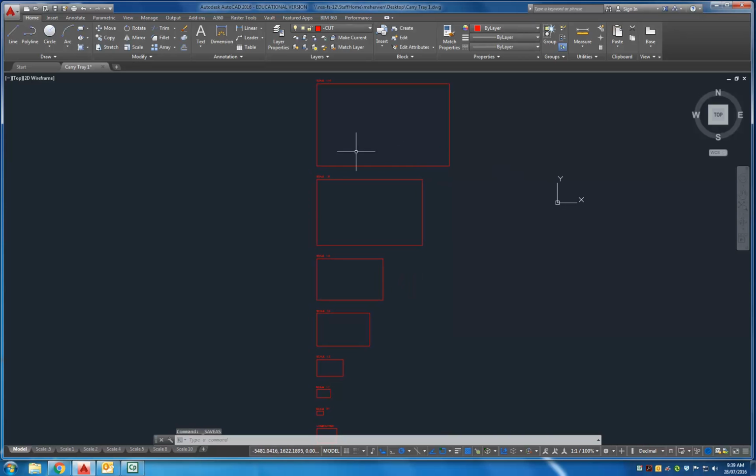From there, I just want to talk quickly, before we start, about what this space is. This is called model space. This is where we do all our drawing. For example, we first find which scale suits our drawing best. If you're creating something small, probably a scale 1 to 1. If it was something a bit larger, maybe scale 1 to 5, or 1 to 8 if it was quite large. So if we drew a circle in scale 1 to 2, then we go down here to scale 2.